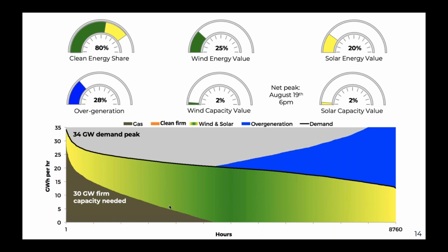And so as we add more capacity to the system to try to knock out gas on this edge, we're also adding a lot of additional generation in the time periods when wind and solar capacity factors are high. So all of that is clustered in this triangle over here in the green or the blue overgeneration wedge. So we sort of have twin sides of the variability coin here for wind and solar, because we get such little generation during the times when we really want to displace gas. We have to add a lot of capacity, and that means on the other side, when wind and solar are generating a lot, we get a huge amount of overgeneration that rises non-linearly as we try to drive up the share of wind and solar.